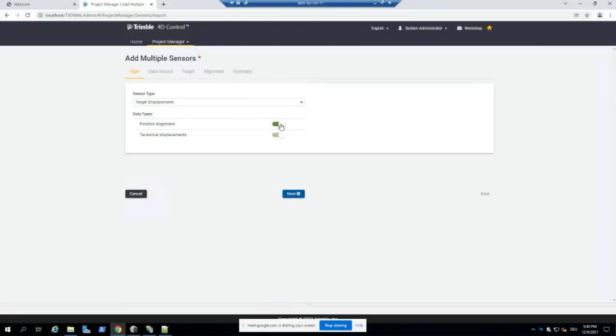If I do so, I can basically associate and tie a certain positional sensor, my prisms, to an alignment file, right? And then the displacement and the report information, everything will then be relative to delta, station, offset, vertical. In my case, I think I will focus on the basic stuff for now, because considering the time, and I do not have, let's say, a proper TXL file or something available at the moment anyhow. So let me just go through the general workflow.